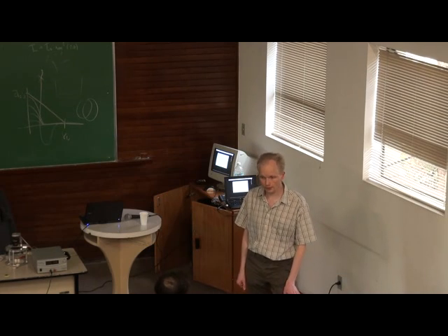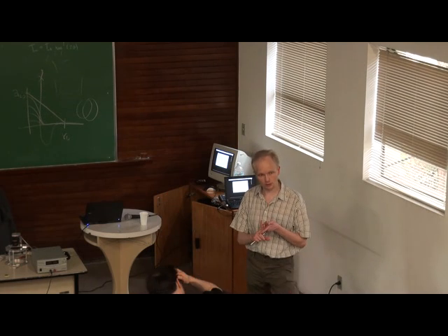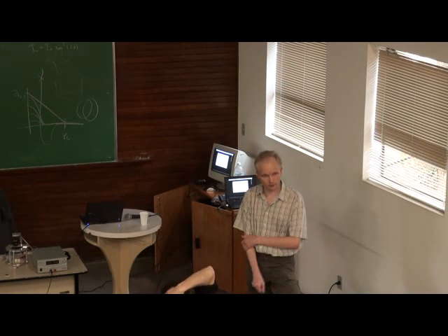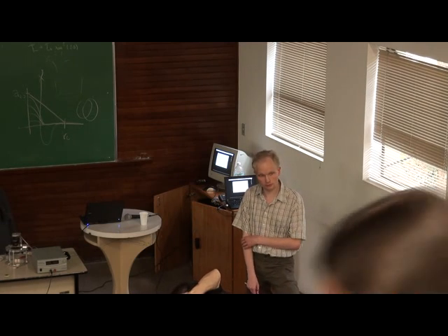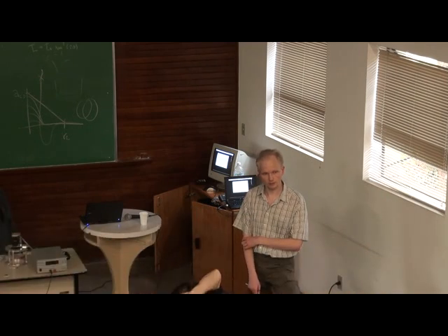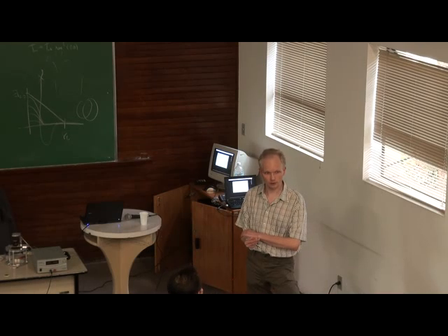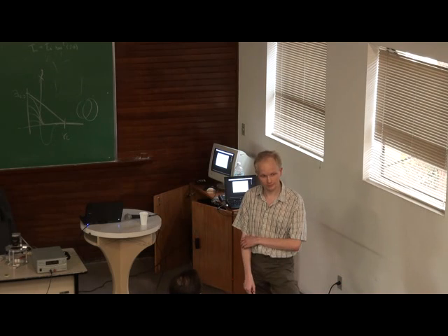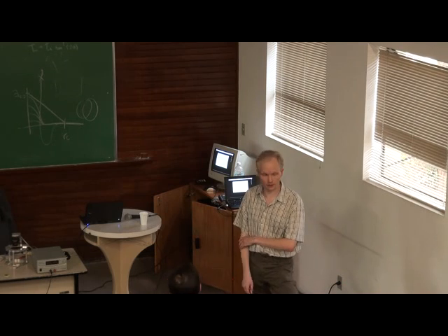And you also have support for particles with orientation. So you could have anisotropic particles with Gay-Berne interactions or similar interactions. That also works out of the box. But I think if you really want to use AMBER or CHARMM kind of force fields, GROMACS is much easier to run than LAMMPS. For coarse-grained things, I can recommend LAMMPS.